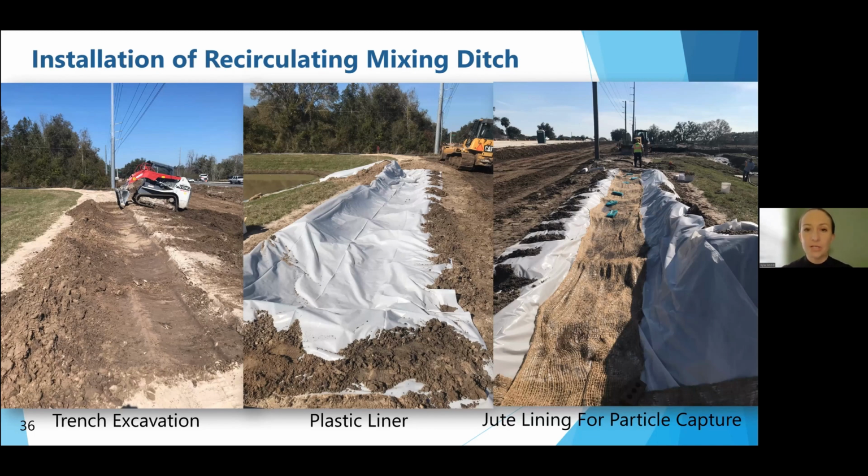So the more mixing and reaction, the better. We don't want to put our logs right at the end of the channel, where they have a split second from the time the water hits them until they discharge into the pond. Because if they're in the pond, that's considered more stagnant, even if there's some slow flow. It's not going to be enough to form those flocs. So we might get the polymer in the water, but we're not going to fully form flocs.